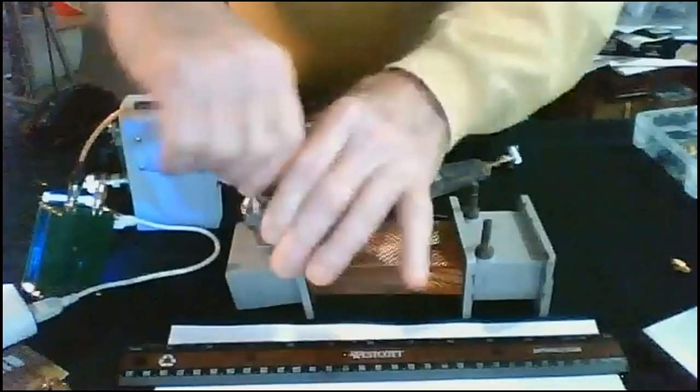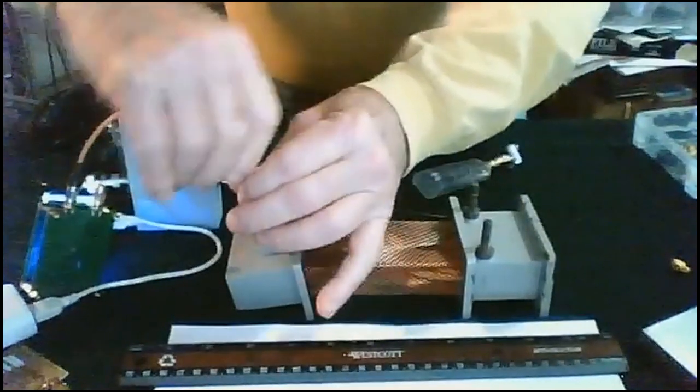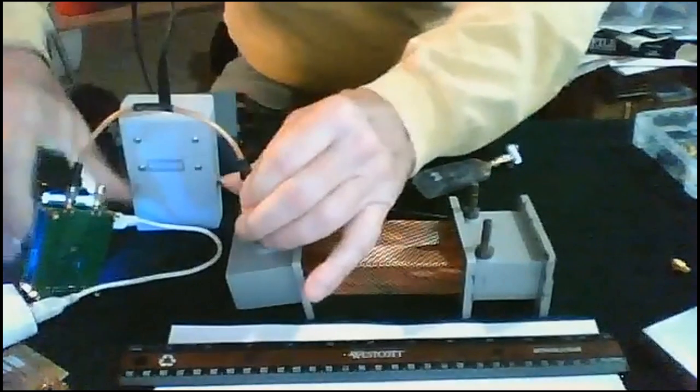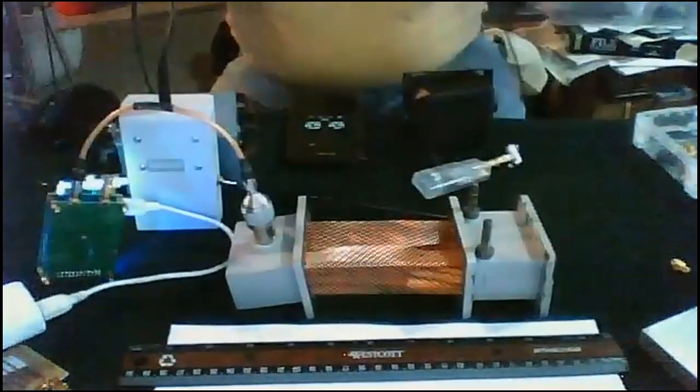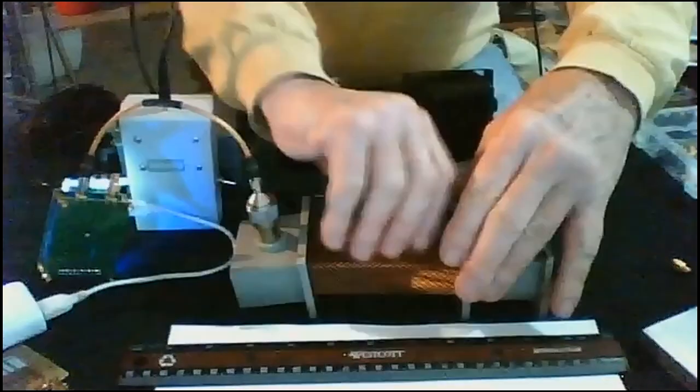Have you tried putting something like Teflon in the open hobby brass tubing to see that the wavelength changed? I haven't actually done that, but that would be a very good experiment. You could also immerse it in liquid and figure out the dielectric constant of the liquid. I just think so many amateurs want to know about velocity factors in coax, and right now they just look it up on a table, but you could actually demonstrate that. That would be fantastic. That would be a good idea, yes.